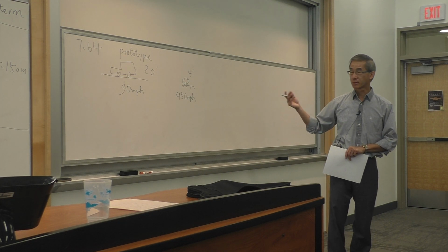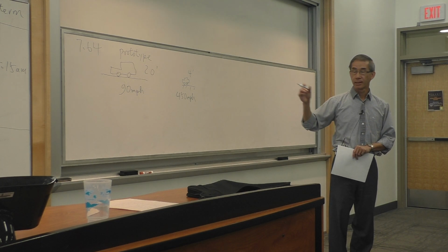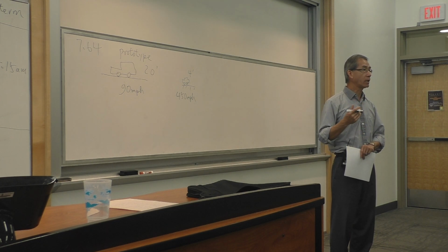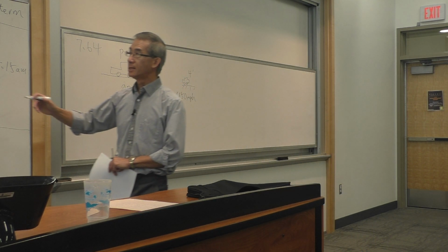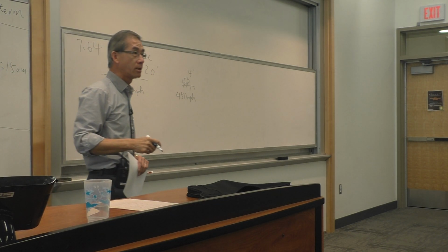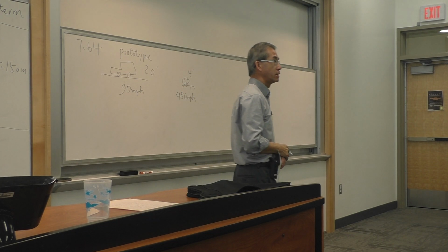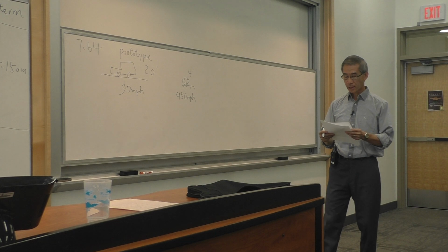At 400 miles per hour, there's a shock wave, which is not what you see at 90 miles per hour. So you're not quite matching another dimensionless parameter, which we didn't touch. That's called the Mach number. So the takeaway is, it seems very simple and easy to claim this matching, but in real life it is not typical. So that's example one. Example two is actually the airplane,